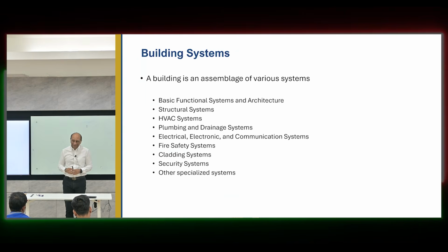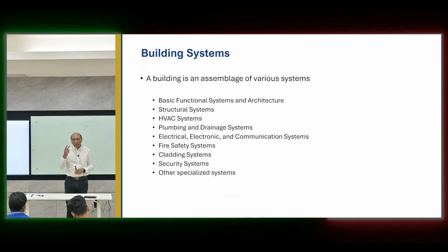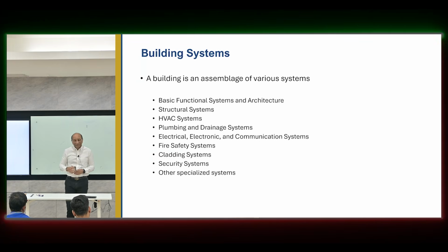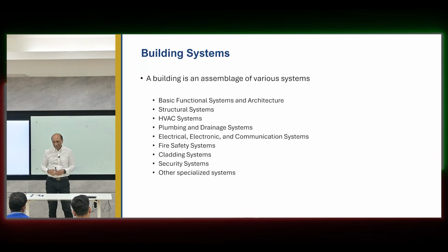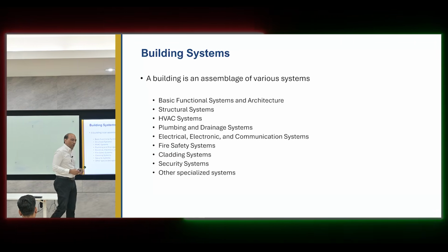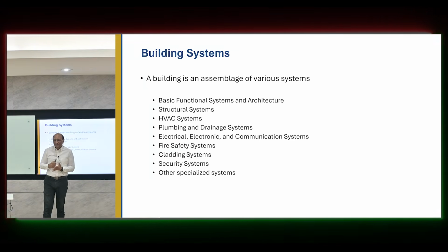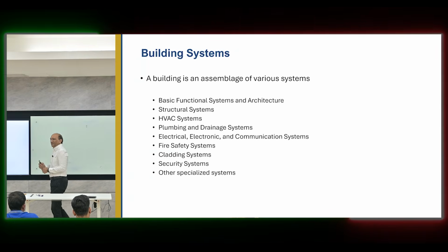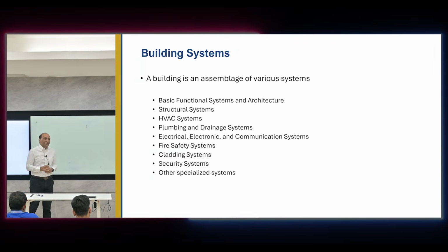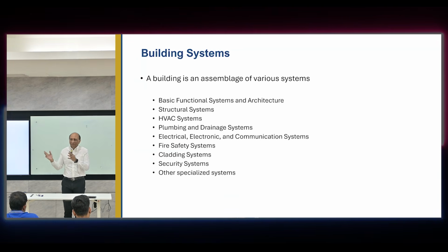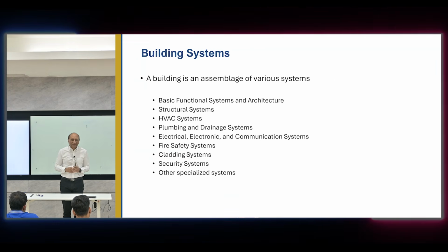Can you imagine that? 2% up to 3% is possible. So it can go as high as 9 meters, right? In an extreme case. Still, the building should not break, should not fall, should not cause damage. That's the kind of movement we are looking at. Even for normal wind, it will be more than a meter. Just the daily movement of a building of that kind is more than a meter.